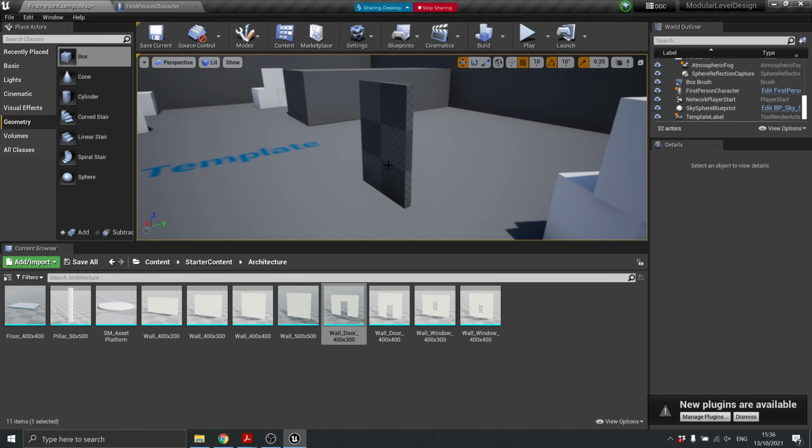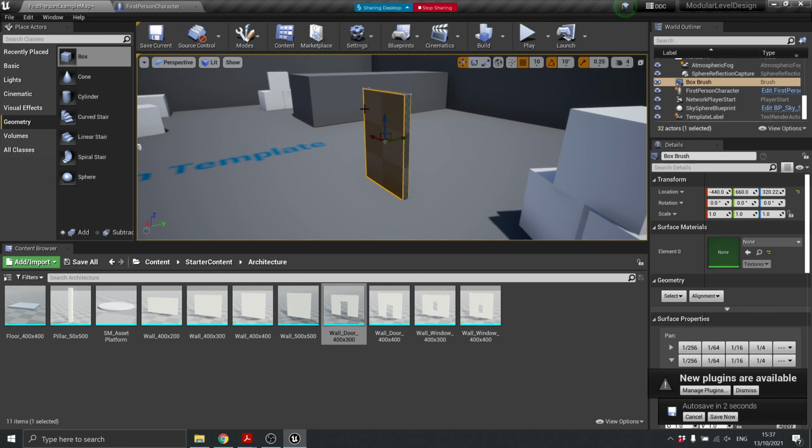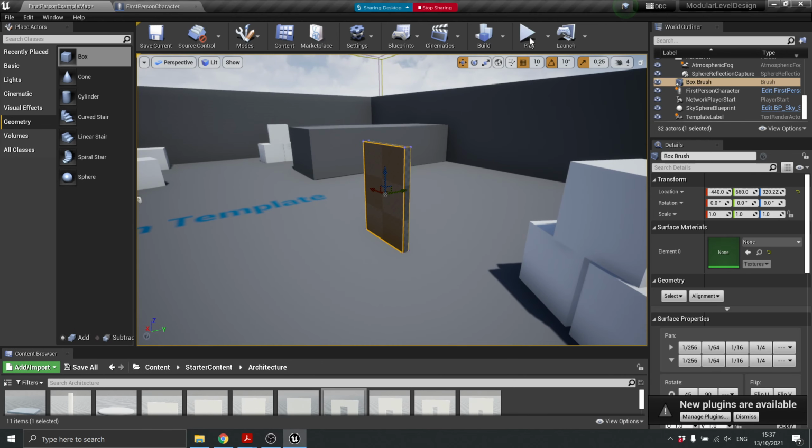Okay. And your goal for the next week is going to be to take the level layout you've done at this stage, and you're going to turn it into a sci-fi environment with some more detailed modular assets. Okay. So we'll see how we can use this technique to make this asset look a little bit more interesting, like the corridor you might see on a spaceship. Okay, and to do that, I'm going to select this brush, hit F. I'm going to try and make the screen a bit bigger as well.